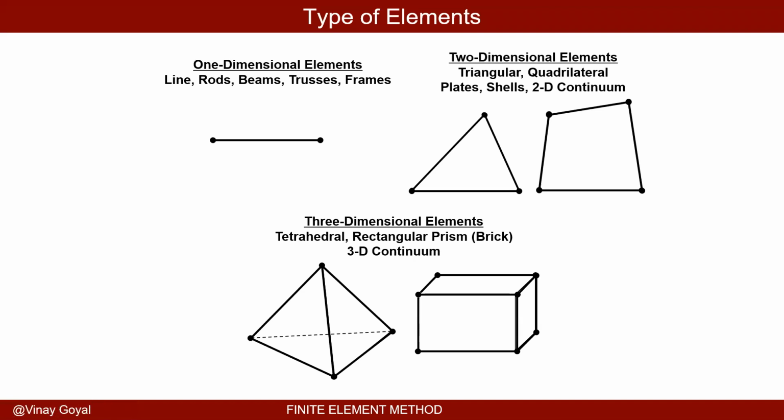We then have the three-dimensional elements, which is the subject of what we plan to discuss right now, and it tends to be the more computationally intensive and expensive. Here you see a tetrahedron, and here you see a hexahedral, or a brick element. These elements can be used to discretize a three-dimensional domain for which you cannot use the simplifying assumptions of the one-dimensional theory or two-dimensional theories. If you cannot fit the criteria for modeling in this way, then you have to go to a three-dimensional type element, which is computationally expensive.